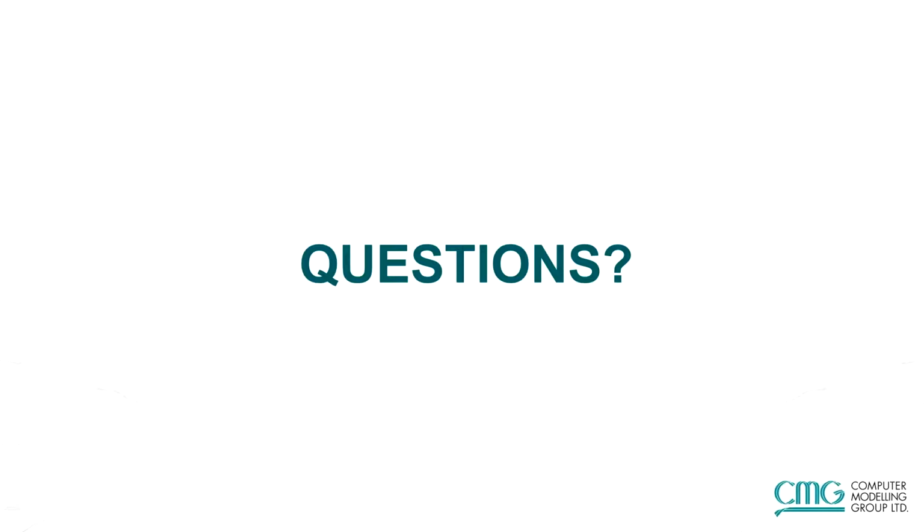So I understand, Kodai, that you are asking about coupling geomechanics using a third-party simulator. So that can be done. We have a feature which was introduced last year. It's called Outboard. So I'd encourage you to look in our manual about the Outboard feature, and using that you can export the pressure and temperature to the third-party simulator and take the properties back into the CMG simulator. So both the geomechanics simulator and STARS run concurrently, exchanging information between the two simulators.